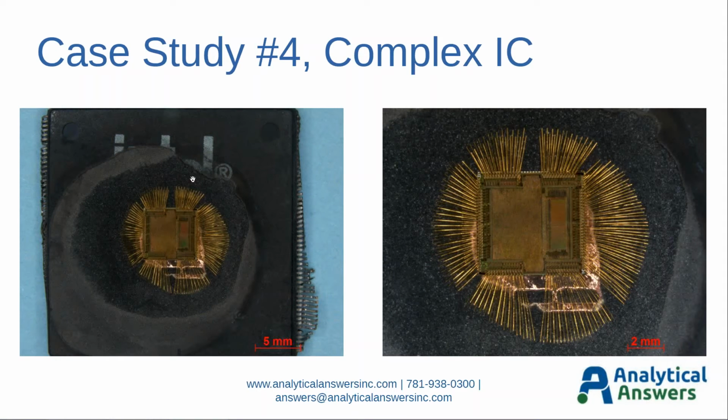So I went ahead and actually performed a wet chemical de-encapsulation processing of this device, and this is what it looks like after that's done. We can certainly see that the integrated circuit is exposed here. This is an optical image of that. Here's a higher magnification optical image of that integrated circuit.